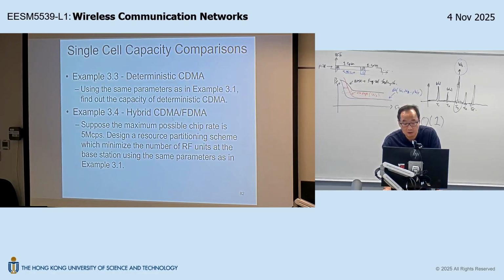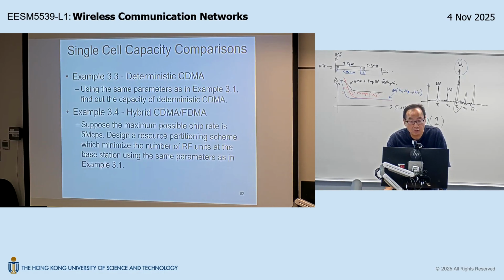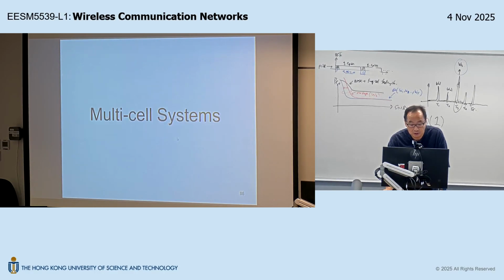So now of course, one reason for using CDMA is for 3G system, the transmission bandwidth is much larger. So if you do not use CDMA, you have to live with this long channel memory. You have a severe intersymbol interference. So one motivation of using CDMA is it helps you to overcome this severe multipath effect, okay? And so therefore, it can help to push the error floor lower and lower. That's one important motivation. But in terms of capacity, seems like there is not much benefit at this point, right? Now we'll keep this in mind for this question, okay?